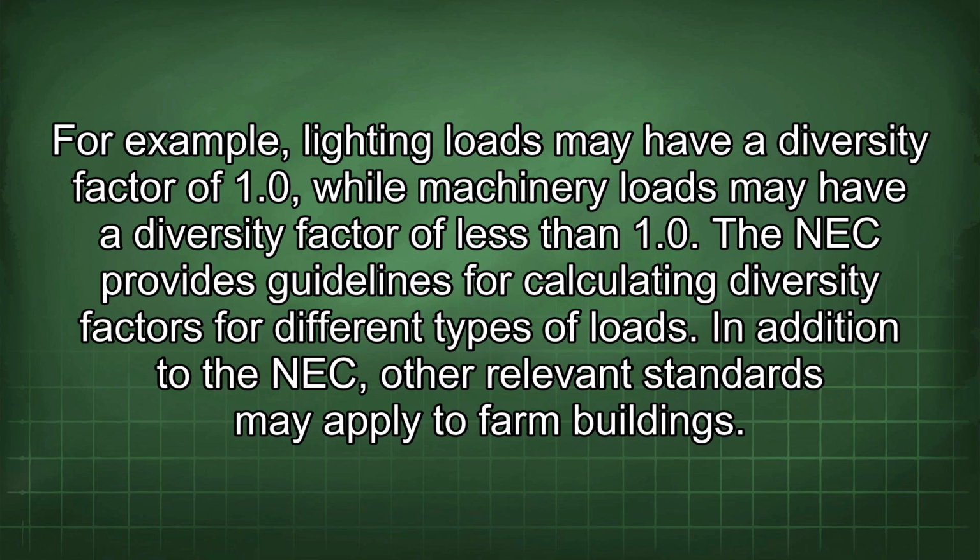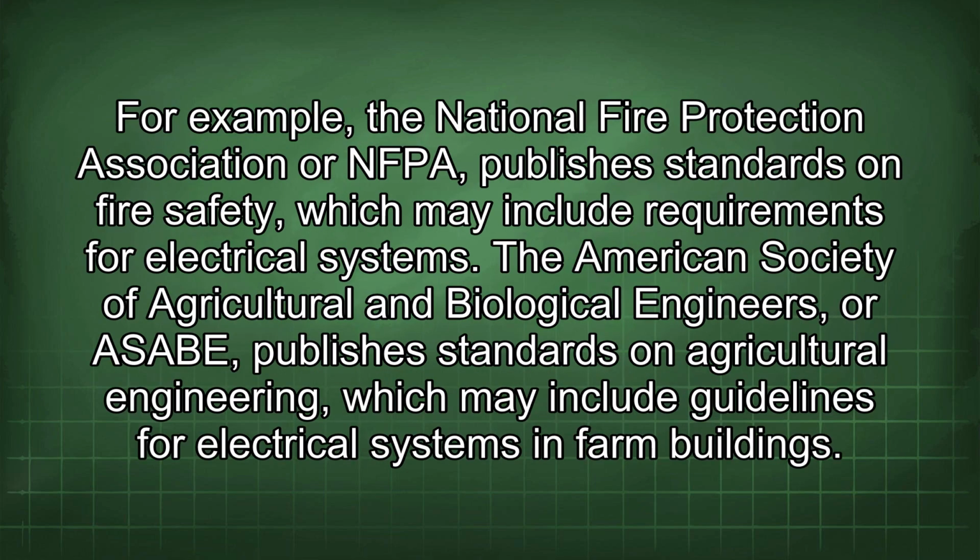The NEC provides guidelines for calculating diversity factors for different types of loads. In addition to the NEC, other relevant standards may apply to farm buildings. For example, the National Fire Protection Association, or NFPA, publishes standards on fire safety, which may include requirements for electrical systems. The American Society of Agricultural and Biological Engineers, or ASABE, publishes standards on agricultural engineering, which may include guidelines for electrical systems in farm buildings.